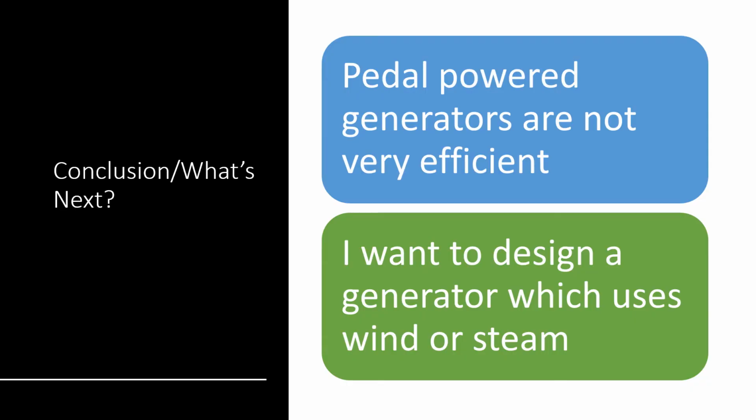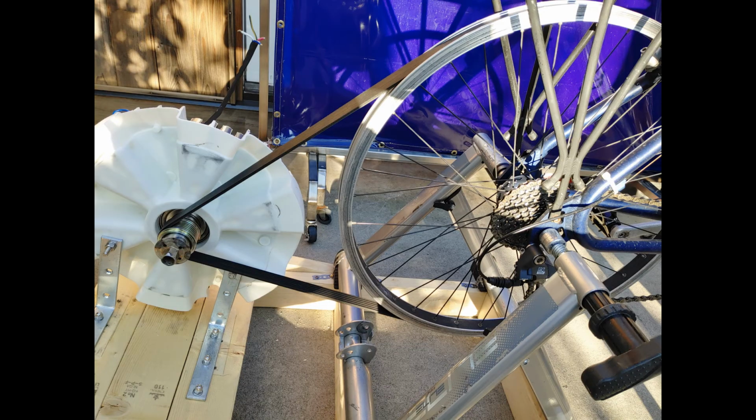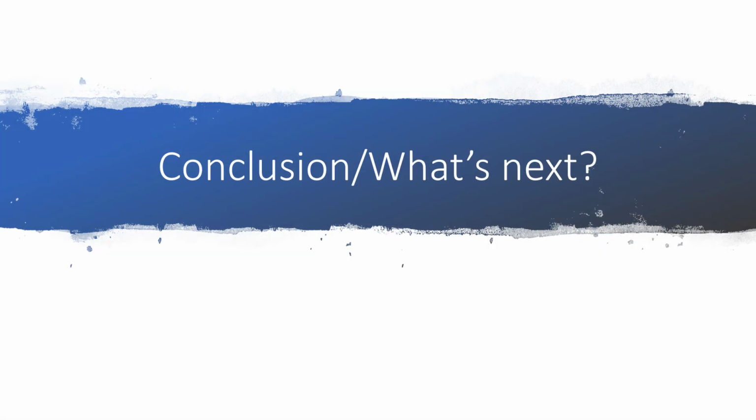My system was successfully able to charge a battery, and the battery could charge a phone. However, the alternator was extremely difficult to spin and did not generate that much current. The rider would struggle to keep the alternator excited and generating power. Using a permanent magnet motor would be much more suitable for a system like this. When the belt was connected to a motor from an old washing machine, which does use permanent magnets, it was able to generate up to 1,000 volts in AC.